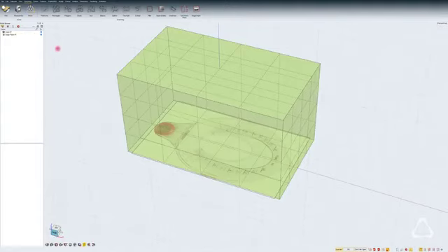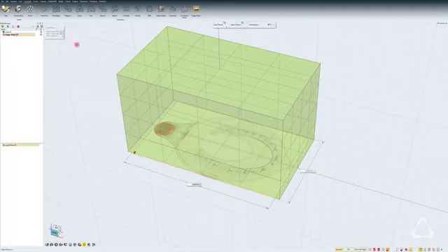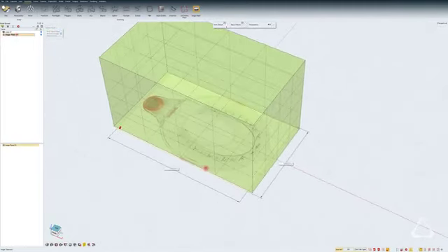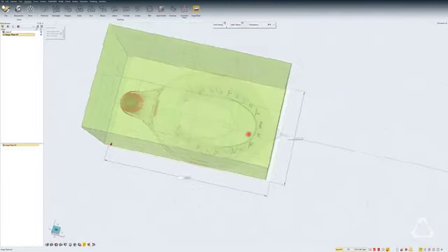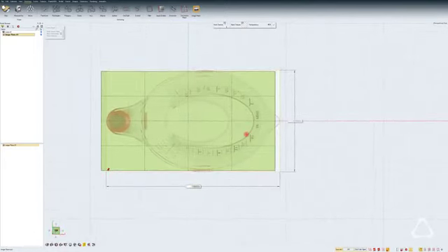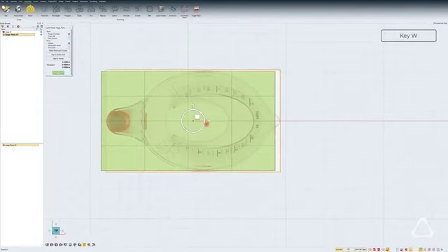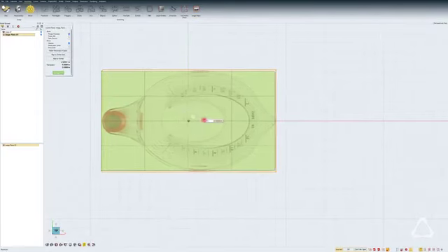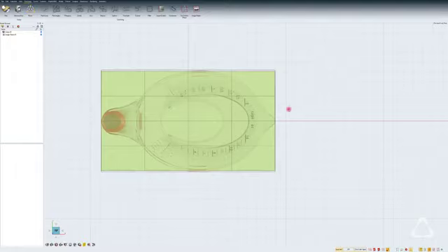To edit the image plane, we can just double click on the object in the model browser, and here let's turn off the keep aspect ratio so that we can manipulate the size unevenly. And for the length, I'm going to type in -7 to make it slightly longer, and you can see that in the top view I think the length is fine. I just have to move the image plane to the center, for which I can use one of the grid snaps, and right click swipe to complete this operation.